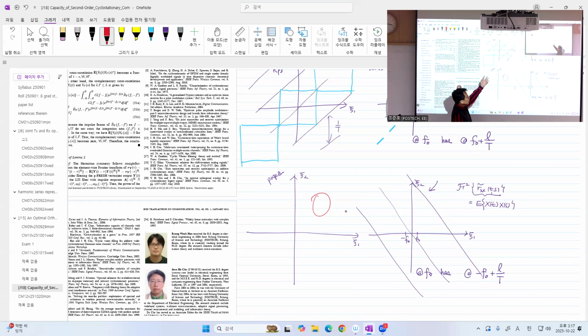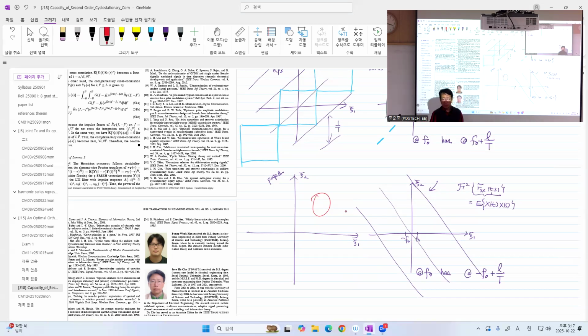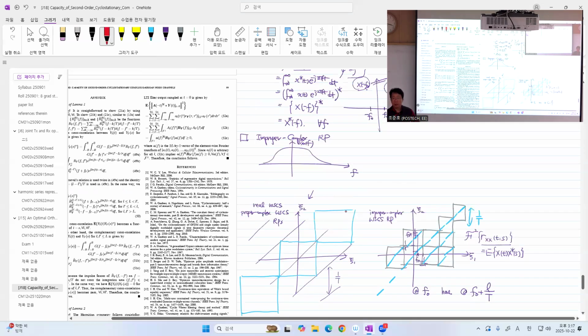So you not only have an ordinary bispectrum, you also have a complementary or pseudo bispectrum that has impulse fences with spacing 1 over capital T. But the direction of the impulse fences is opposite to that of the original impulse fences here. Got it?